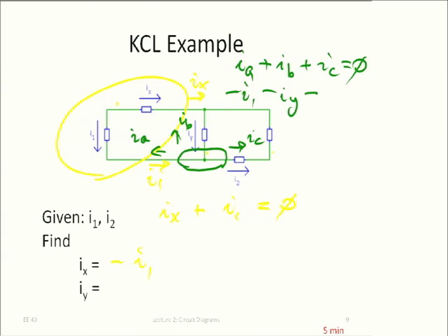Okay. So obviously, like your colleague did, you can do this much more quickly than the way I did that now. But in case you're a little bit confused, or it's the first time you do this, well then, again, draw some kind of a shape. It must be a closed shape, and then introduce arrows for all the currents that, for example, leave that shape, or for all the currents that enter the shape, your choice.